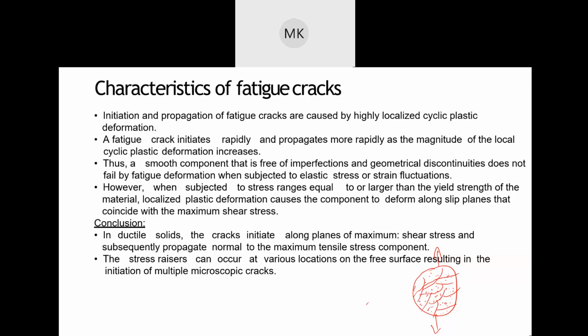Every time, once there is a crack generated, let's say there's a crack like this, there is a plastic zone that is generated at the edge of this crack, and the plastic zone grows in the shape of a kidney bean. And the reason why this plastic zone is there is that all other regions in the material are in the elastic limit.